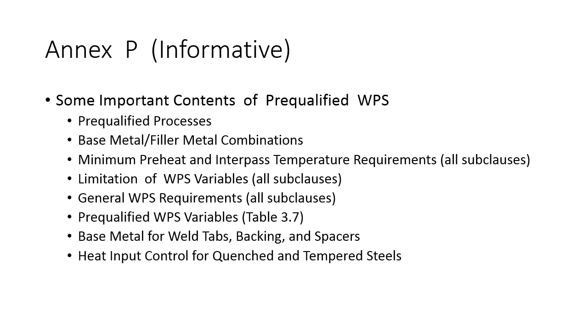So it's going to tell you, is it one of the pre-qualified processes? I'm using electroslag welding. Nope, it's not a pre-qualified process. Can't use electroslag welding. Oh, we're using shielded metal arc welding. Yes. Are my base metal and filler metal combinations two that I can use? Yes. Did I get the preheat and interpass temperature requirements? Yes.